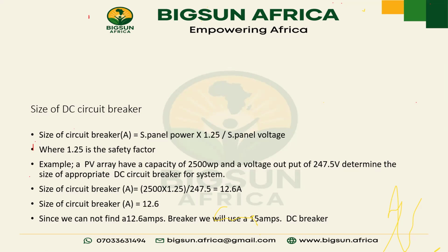Okay, so let's now proceed. We have 9 panels of 560 watts, and we're assuming that the VOC of each one is 51.5. There are two things. If you are working with a hybrid inverter that is maybe 500 volts, you can have your whole 9 panels in series, or you can decide to have your panels 3 in series.